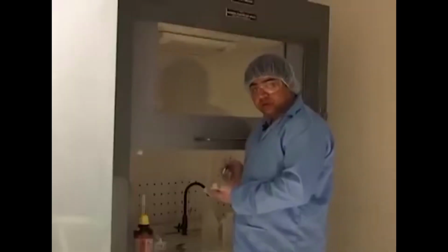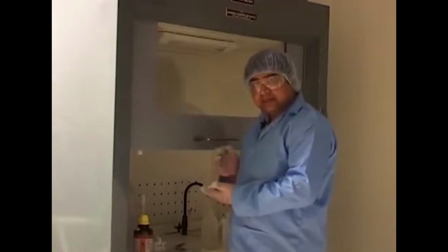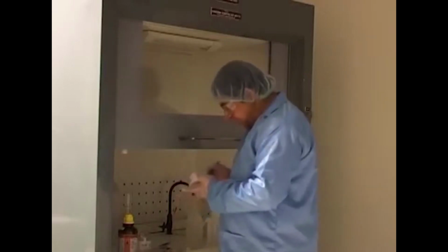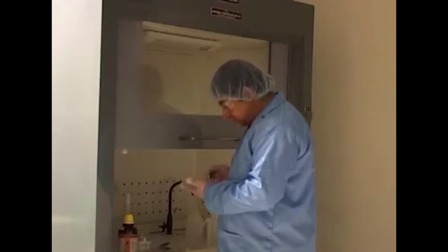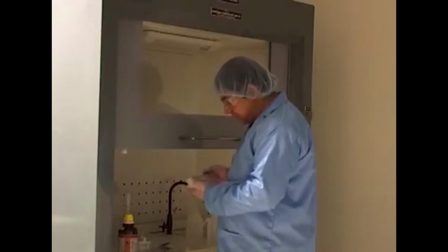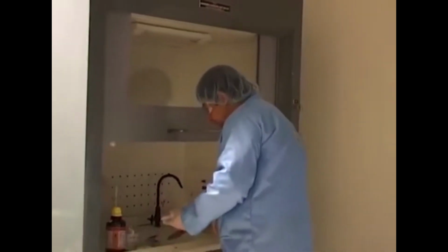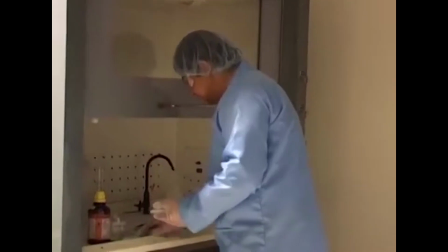One thing we also have to take care of is that you cannot simply drop the wafer into the developer. You have to keep stirring the developer solution from time to time so that there is no accumulation of the unexposed resist which is coming off at one particular place. The idea is to keep dissolving it by swirling the fluid over it in a particular manner. So I am going to do that, and after 4 seconds I am also going to spray isopropanol to see whether the resist is totally developed or not, and essentially start the time now.